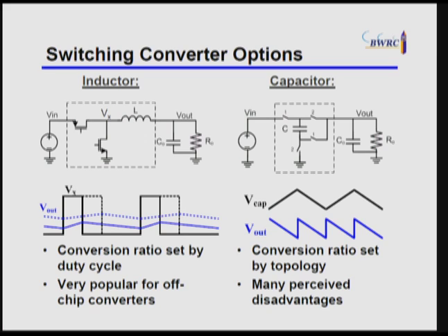There is, however, another potential option, and that's the so-called switch capacitor type of topology. The idea with switch capacitors is that you connect a capacitor, for example, either between the input voltage and the output voltage, and then in the next clock phase between the output voltage and ground. By doing this, you can set it up so that there's effectively a division of the input voltage based upon how you configured that capacitor. Now, if this doesn't make immediate sense to you, don't worry. I'm going to say in a lot more detail how these things really work.